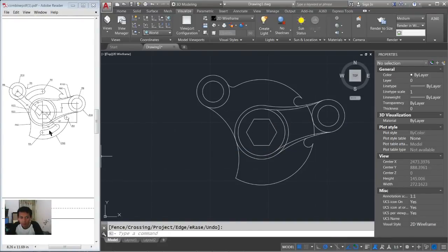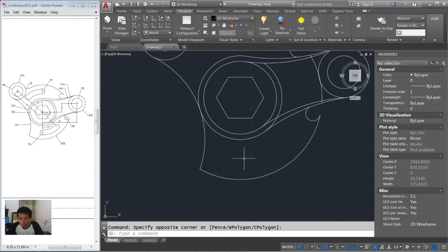Okay, next I will create this object. First, you can create a circle with radius 4 in the center of this object. Okay, I will create a circle, and you can type M2P, middle between 2 points, enter. Click the first point in here, and then click the second point in here. Okay, it will be created in the center here with the radius 4 and enter.